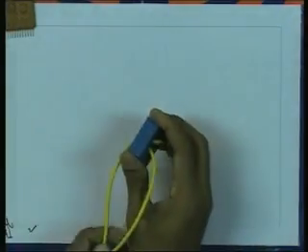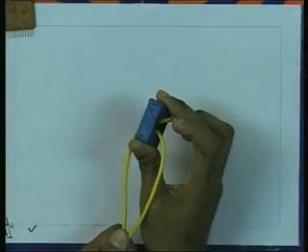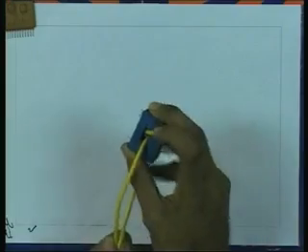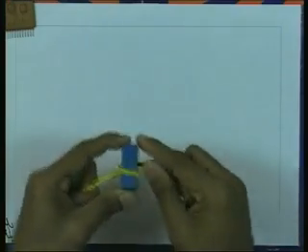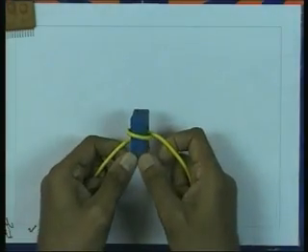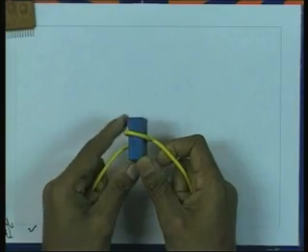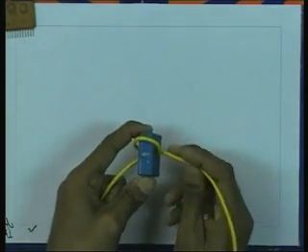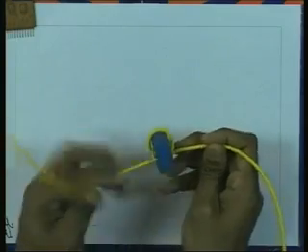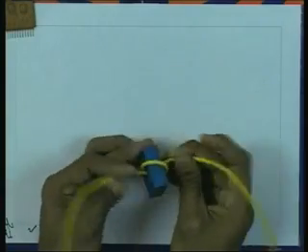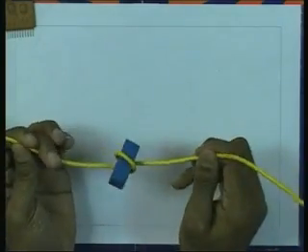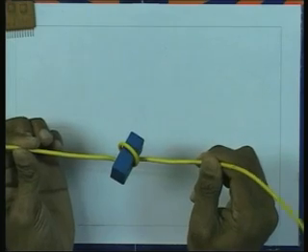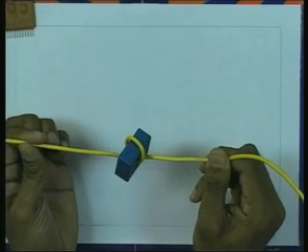See how small a current sensor is. It works similar to a current transformer. The rating is 50 ampere turns. In the sense, I have put only one turn here, so I can supply as high as 50 amperes of current through this.